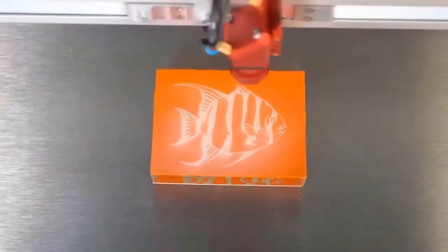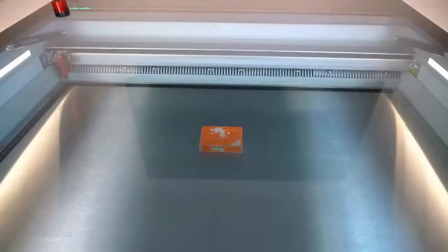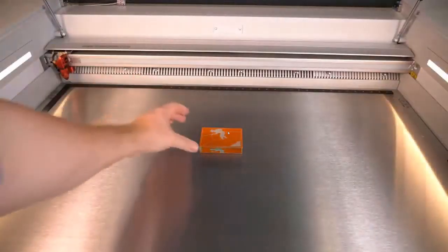We're going to ablate the surface of the Blazer Orange, and then we're going to slightly go into the glass. I like to just kiss into the glass a little bit. This way we get a nice clean removal. It doesn't hurt the glass at all. If you overpower it a little bit, it's not going to hurt anything. Or in this case, where I'm just barely going through on this little rock climber one.